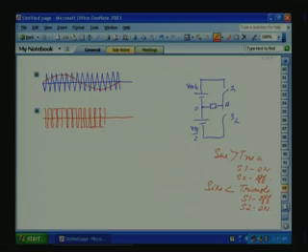So now this is the negative portion, the negative side. After 180 degrees, the pulse width waveform pattern is exactly opposite to that of the pattern before 180 degrees. Okay. So the fundamental, if you see here, we can use a different color for clarity. That fundamental will be like this.